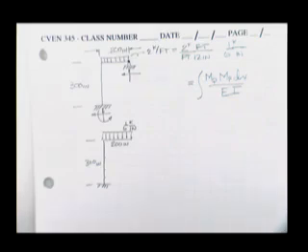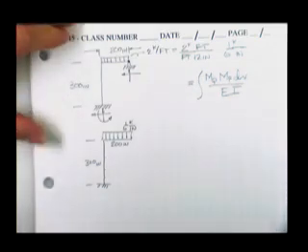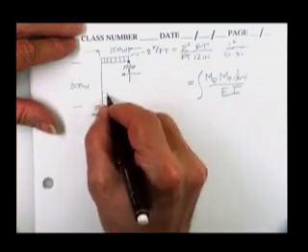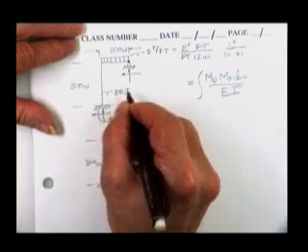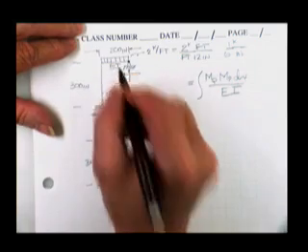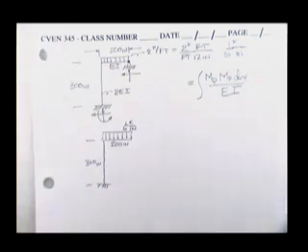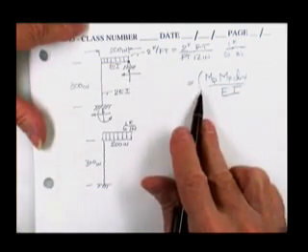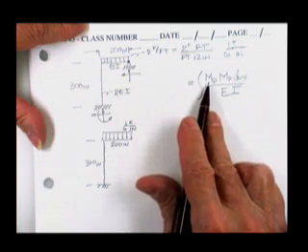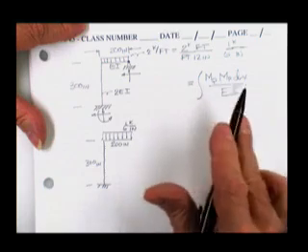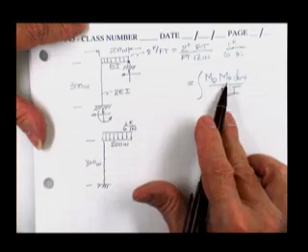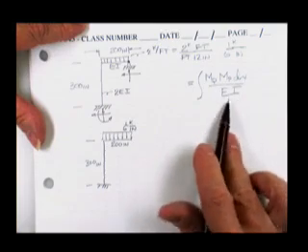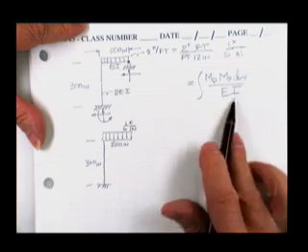Incidentally, I need to go confer with the boss about these members. I asked him, are these all the same? And he says, well, no, this is a column, and it's got 2 EI, and this one has EI. I say, well, I do need to know that. That's going to change the answers. Therefore, it's up to you to go get a unit load on this thing and find the moment diagrams involved and put the real loads on this thing and find the moment diagrams involved and integrate them dx over EI, where EI doesn't mean EI. EI means whatever your EI is.